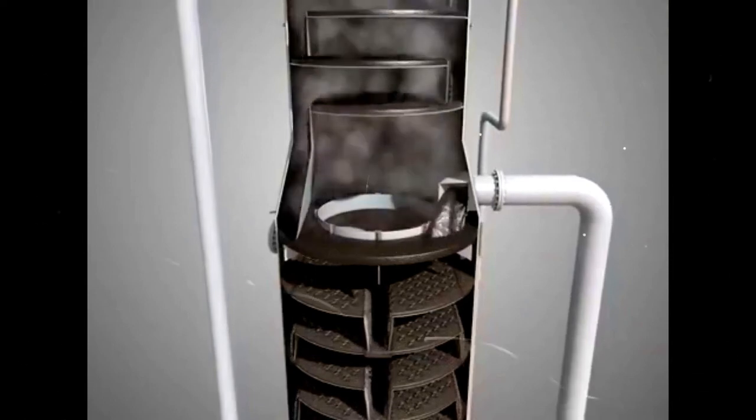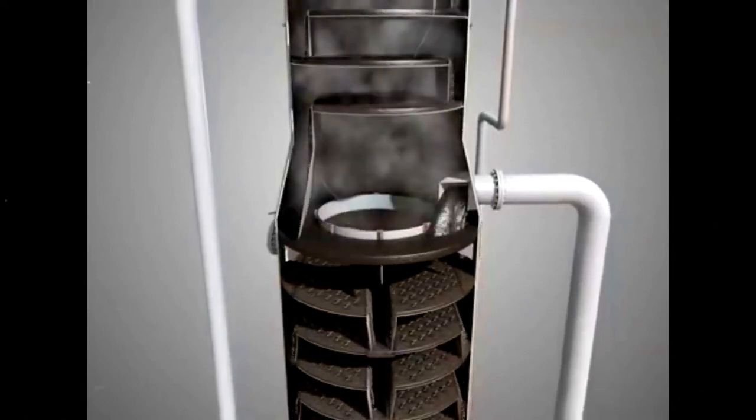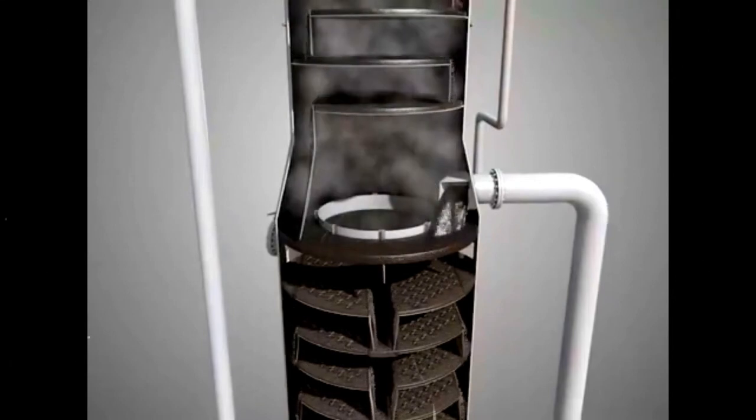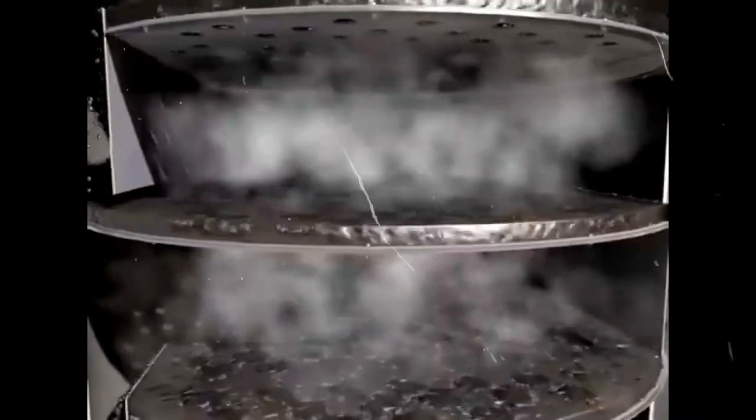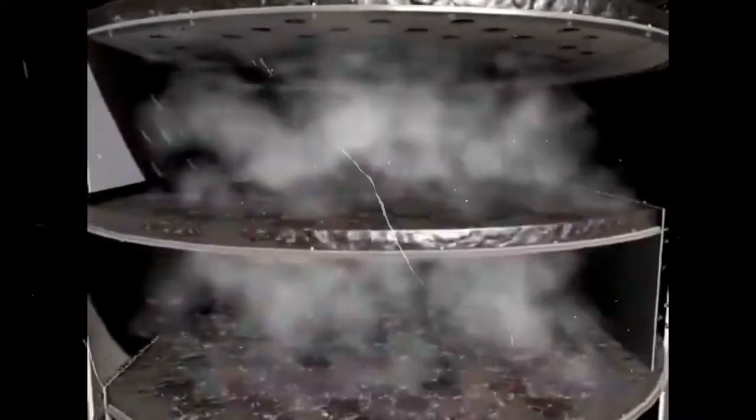Sieve trays, which are perforated thin plates, are very good in fouling applications or when there are solids present because they are easy to clean. However, the turndown, the performance when operating below the designed flow rate, is relatively poor. Valve trays are designed to have better turndown properties than sieve trays. Therefore, they are more flexible when the feed rate varies.